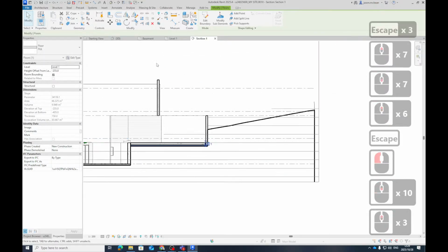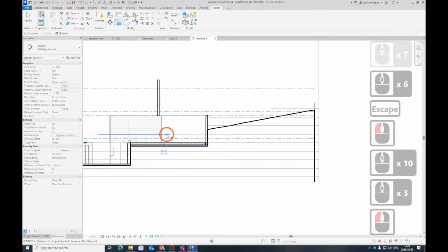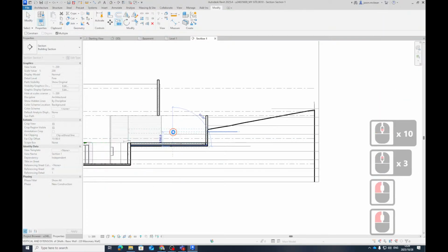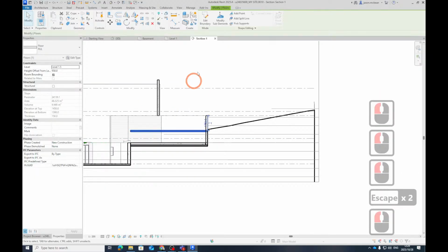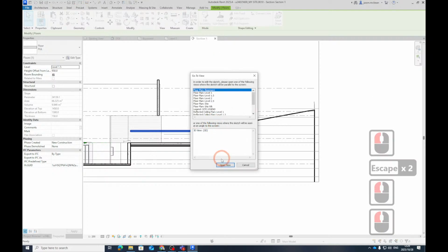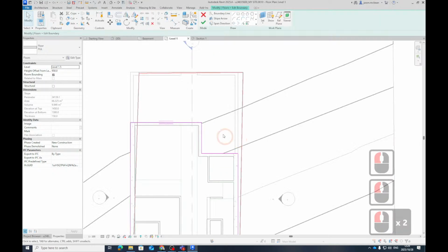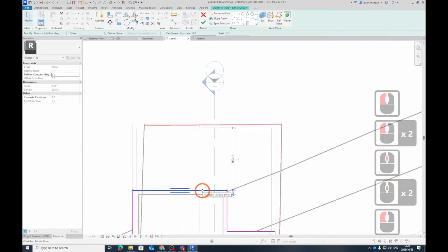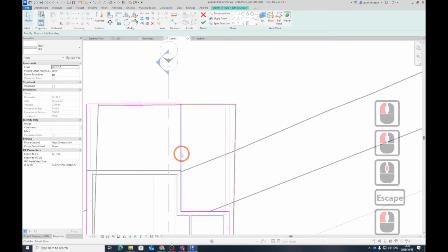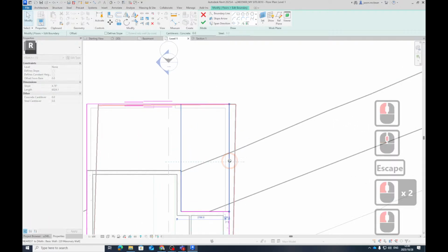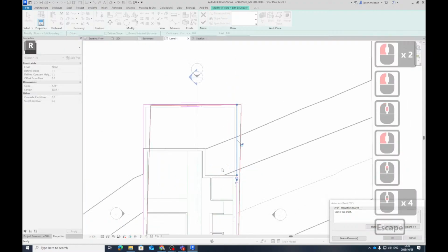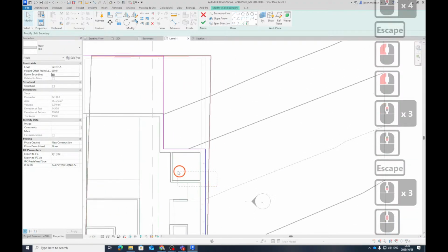So I'm going to duplicate this again. I'm going to say copy, and move this up. Now this one, I'm going to say edit boundary. This might be level 1 for now, but now I'm going to take this to the outside. Oh yeah, you can't have a 0 in Revit, by the way. Revit can't have a 0 item, so get rid of that.